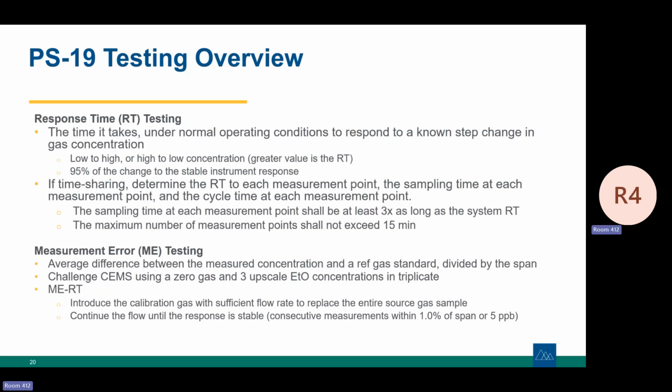Sorry, I know this is a lot of words I'm trying to summarize. Response time testing is looking at the time it takes to do that step change, either from low to high or high to low, to get back to a stable state. Whichever of those steps is greater is going to be your response time. This is especially important that we've seen if you're time sharing these sample points to get those multiple points within the 15-minute period. You need to make sure the response time is sufficient, because the measurement time shall be at least 3 times as long as the response time.